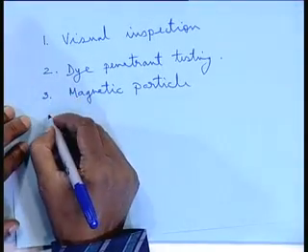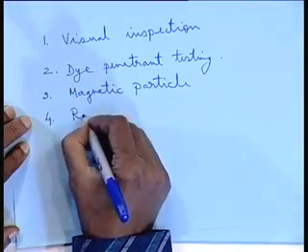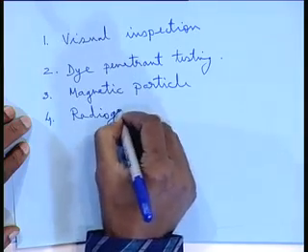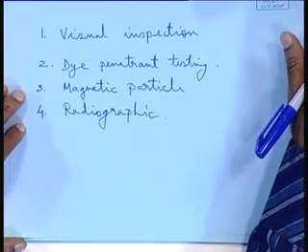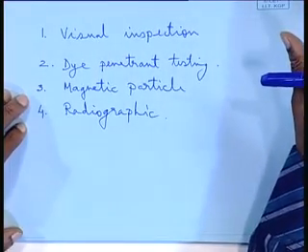Well, next is the radiographic testing. Radiographic testing is nothing but the conventional X-ray as we do, similar to that. It will be more powerful X-ray basically, right. So, the X-ray you all are aware of. In the same method, you will have to put a photographic material below and then you expose it with X-ray. So, whatever defects are inside will get an image there, and again a trained eye has to read that film.